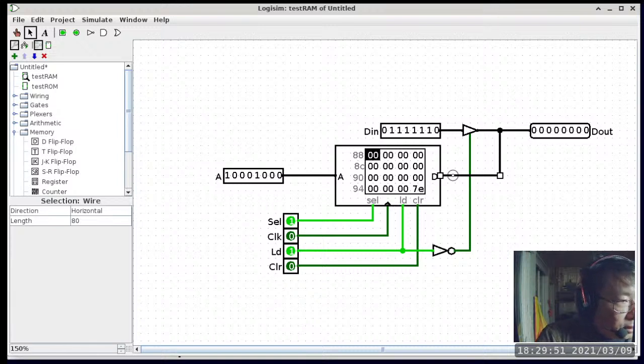All right, so the other question is, as far as I understand, the D port can receive and output data from ROM. Well, if you have a ROM, the D port can only output, cannot input. It's only when you have a RAM that the data port can also input, because RAM can be updated.